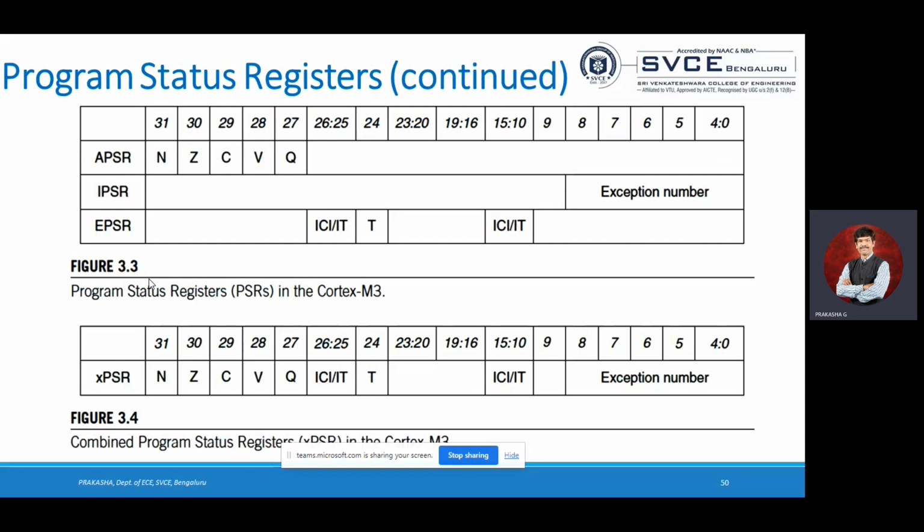Sometimes I will be giving positive numbers only. I may be performing some arithmetic and logical operations in my program. Like I'm going to divide, subtract, multiply, do some trigonometrical operation, and some logical operation. After that, my answer becomes negative. As soon as the answer has become negative, the MSB of the PSR is going to become 1.